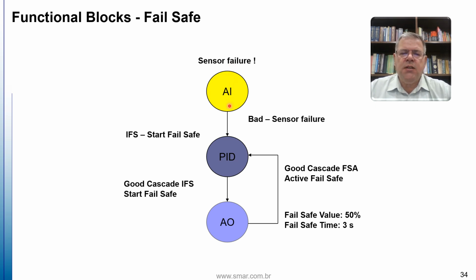The analog input block will send a bad and a substatus for sensor failure. Automatically, the PID block will initialize in IFS, which is fail-safe initialization.